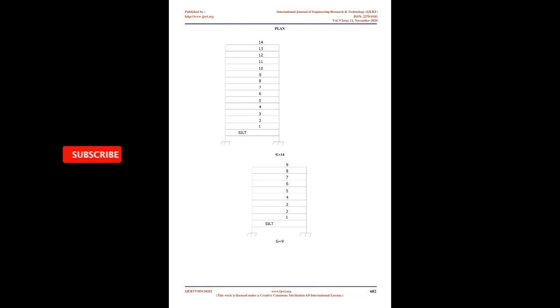The loads or forces that a structure sustains during an earthquake result directly from the distortions induced in the structure by motion of the ground on which it rests. Earthquake loads are inertia forces related to the mass, stiffness, and energy absorbing, that is, damping and ductility, characteristics of the structure. During its life, a structure located in a seismically active zone is subjected to many small earthquakes, some moderate earthquakes, one or more large earthquakes, and possibly a very severe earthquake.